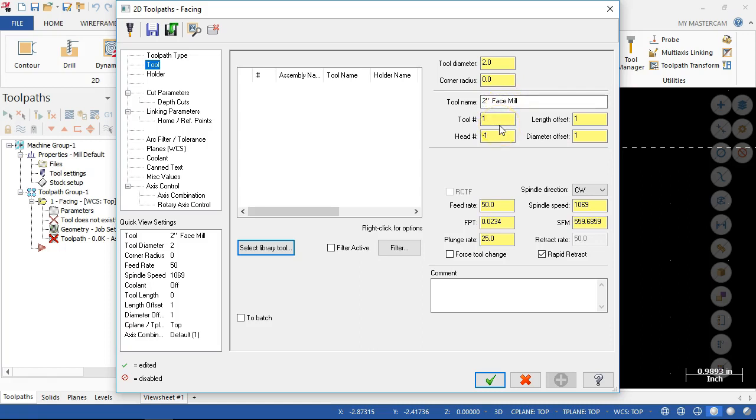We're going to minimize tools. And if you are working out of the beginner tutorial manual, they'll probably have you stay with the 2-inch. I don't particularly care which one you follow. If you're using the Mastercam book, then follow that. I just want to see toolpaths, and I want to see that it's realistic that what you're telling it to do is going to make parts. We're not going to get into this tool over that tool, mostly, especially with aluminum. Any 2-flute or 3-flute end mill, for as long as it has the length of cut, is going to make this part.